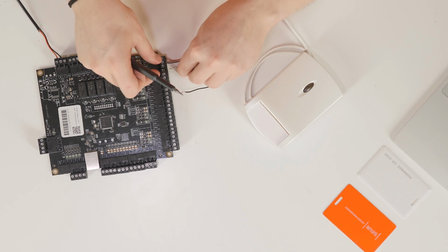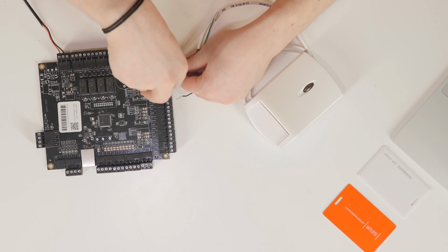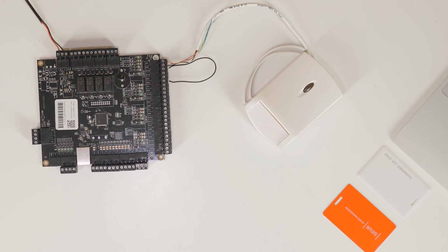Now let's connect the actual interface, the white wire of the reader, to the Data 0 terminal, and make sure to connect a jumper between the Data 0 and LED 2 terminals of the controller, then restart the controller by power cycling. It is important to note here that such a scheme is necessary for the controller to identify the connected reader as touch memory specifically. This means that at the time of powering on the controller, a jumper must be installed between the Data 0 and LED 2 terminals.